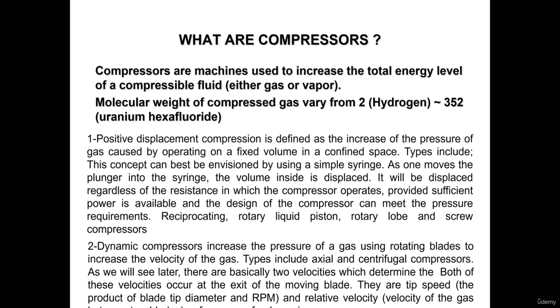So what are compressors? Compressors are machines used to increase the total energy of a compressible fluid, either gas or vapor. That's how they are differentiated from pumps, which handle incompressible fluid, meaning the density of the liquid is not changed by pumping.